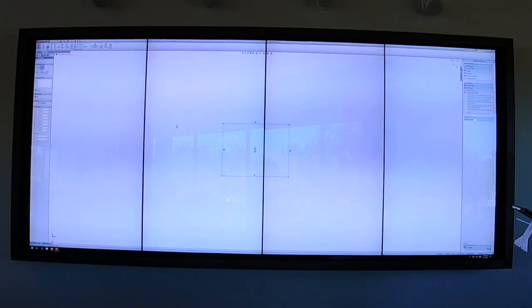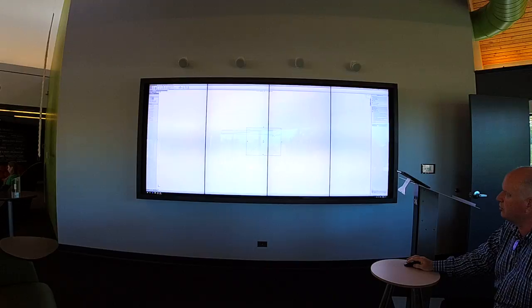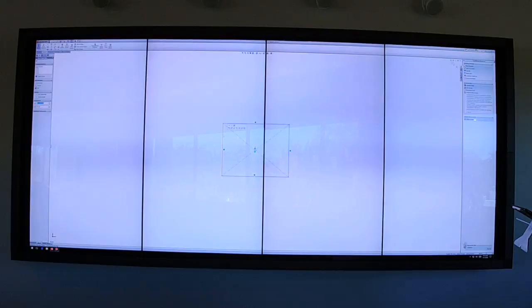Now I've not assigned it any particular values yet. So what we're looking at here is we're going to assign some scale to this. What I'm going to do on the side here, I'm going to select this line, and I'm going to create what we call smart dimensions. So this is how I can assign different sizes to this. If I click on the first line, and I shift and click on the second line, I've now got a section there that I can create a dimension to. It's going to ask me for the size of that. So I'm going to make that, say, 40 millimeters.